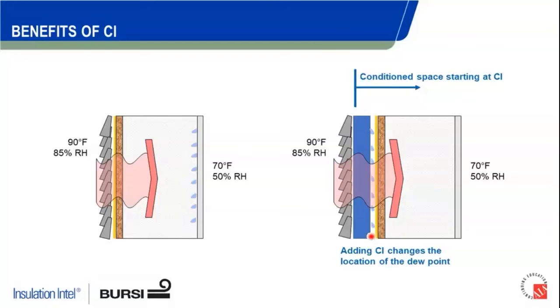And if it's under the conditions where it's occurring steadily and it's not able to dry back out as temperatures change, putting some type of spacer in there can help that water drain out of that system. So whether it be a fluted type board or a crinkle face polyiso, or maybe even literally some type of spacer in there to create a capillary break, that's going to very much help improve the functioning of that WRB, our drainage plane layer we have right up against our sheathing there. So again, just something to be aware of there. Warm climates, doing CI on the exterior still shifts that vapor profile outside of the stud cavity, which is where you want it, but there are other things that may be considered based on where that dew point is occurring.